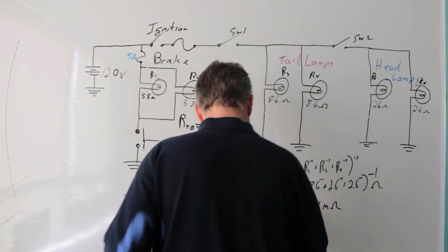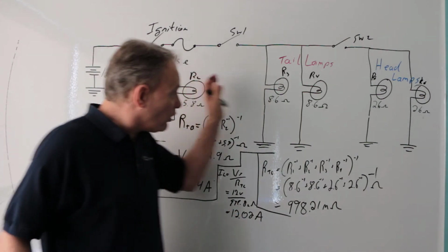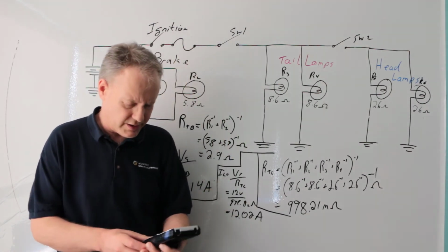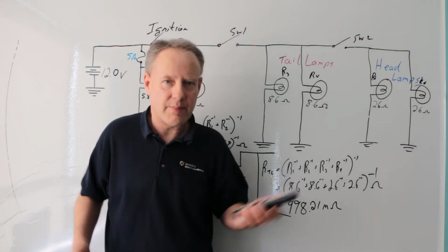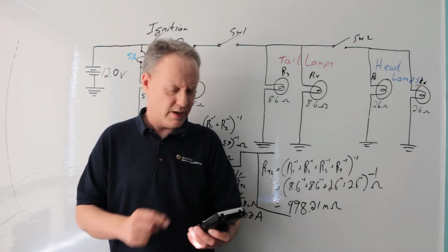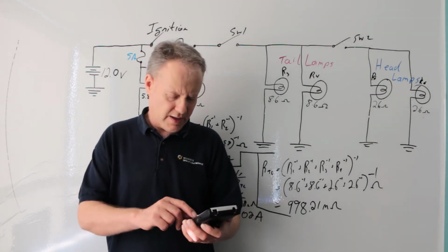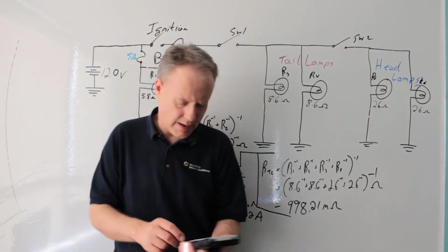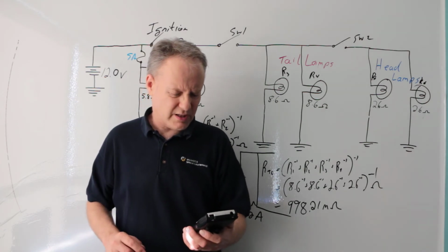12.02 amps. Now, if all of these are drawing 12.02 amps, and that fuse there, well, wait a second, I'm just going to keep that number in my calculator. I'm not going to get rid of it and type in 12. I'm going to multiply that by 1.15, and that is 13.82. Okay, now I'm going to divide that by 1.15, which gives me my original number back. Then I'm going to multiply by 1.35, and that gives me 16.2.